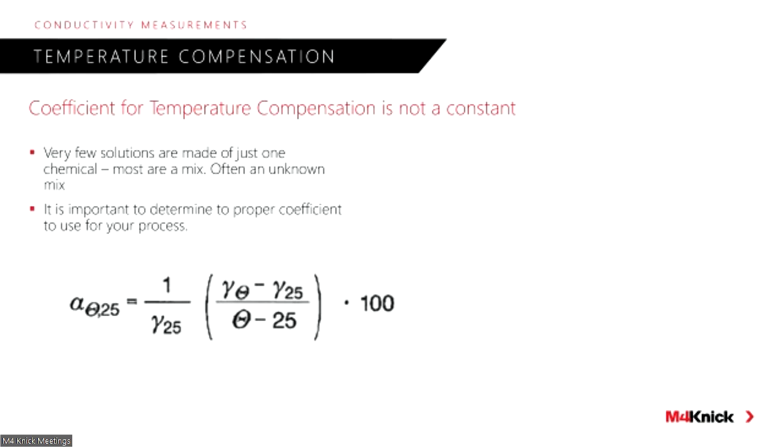You can take that grab sample, take a conductivity reading at process temp, start your data logger, let that sample cool to the reference temperature, and now you can take those values, your conductivity at your online temp and your conductivity at your reference temp, plug them into this equation and calculate your coefficient that would be installed or inputted, if you will,